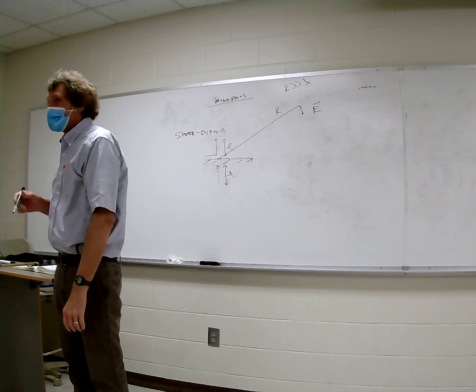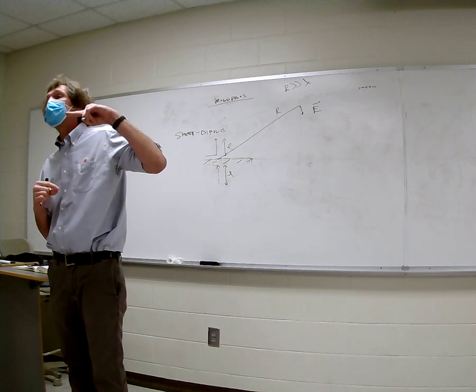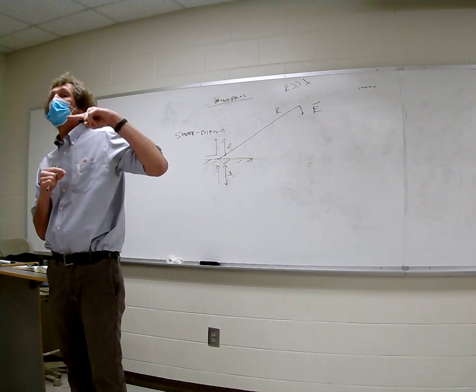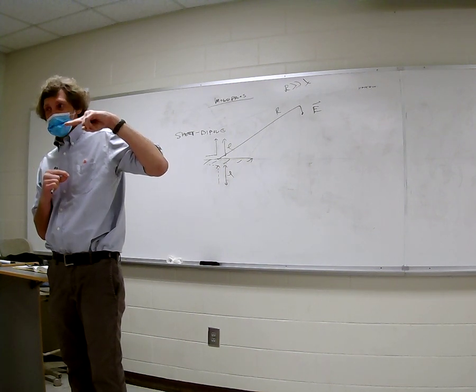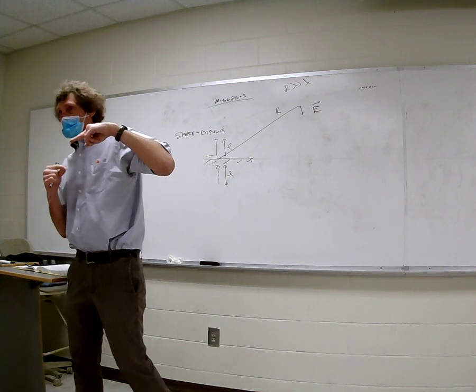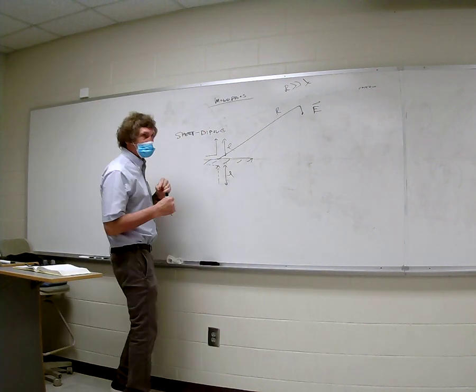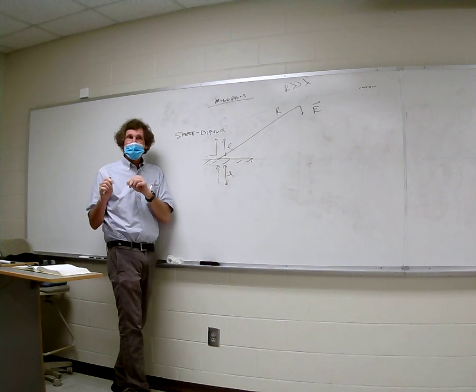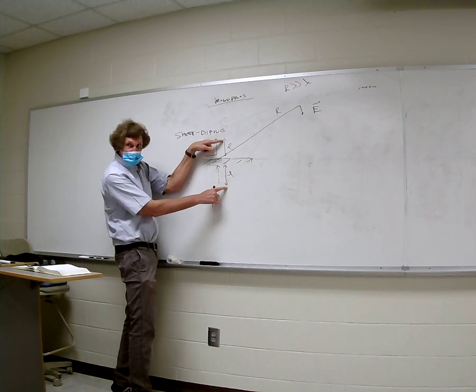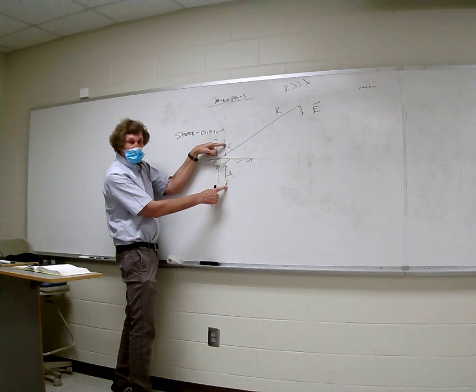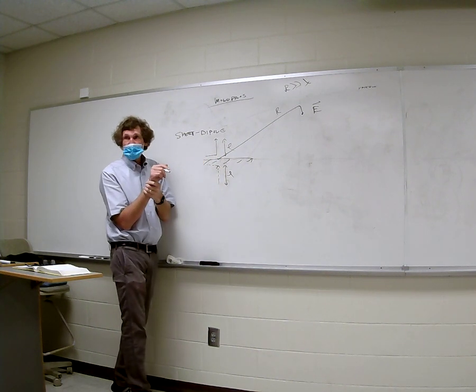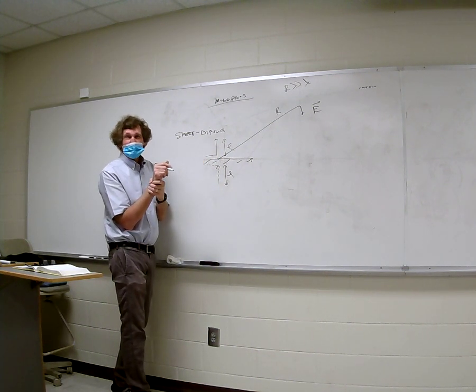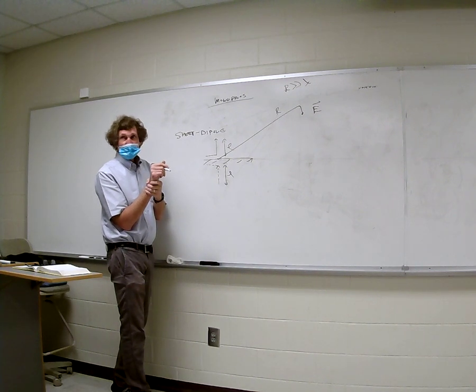What's the length of the antenna? It is lambda over 20 for just the top part. It would be lambda over 10 if this total length, the image included, is less than lambda over 10, then it's short. If it's greater than that, not so much. Once you get close to about a quarter wavelength, then you have to go to the formula for arbitrarily long straight wire antennas.